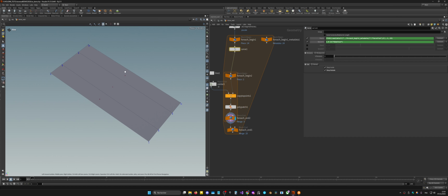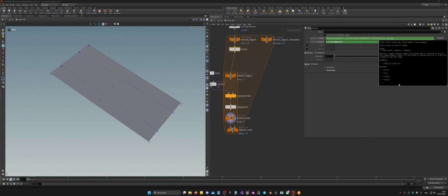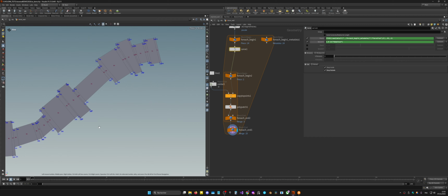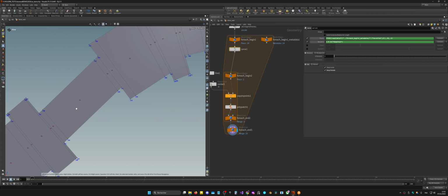It's the same, but now I have my stone and my joints, and I can adjust to say maybe I can go very low value, 0.1, and maybe 0.2 maximum. So the joints are smaller. I will check the results, and now for each stone, you have the main stone and the joint.